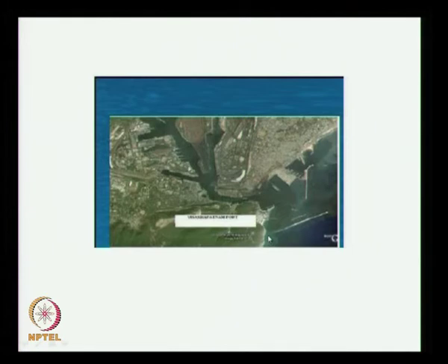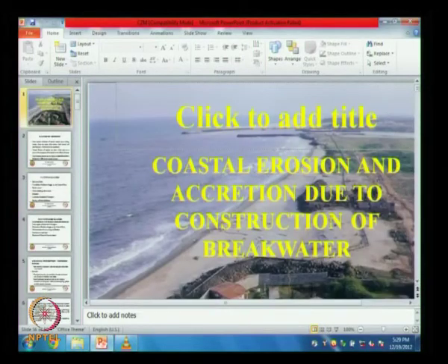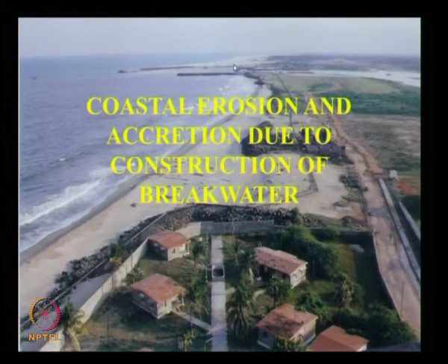One of the first slides which I have shown in this lecture is your Pondicherry fishing harbour. Actually this is your southern breakwater, they did not start from the shore, they have put an approach bridge, then they started, but they did not dredge inside for artificial nourishment in the sand trap, that is why the whole bridge has got closed and the shoreline also has advanced.